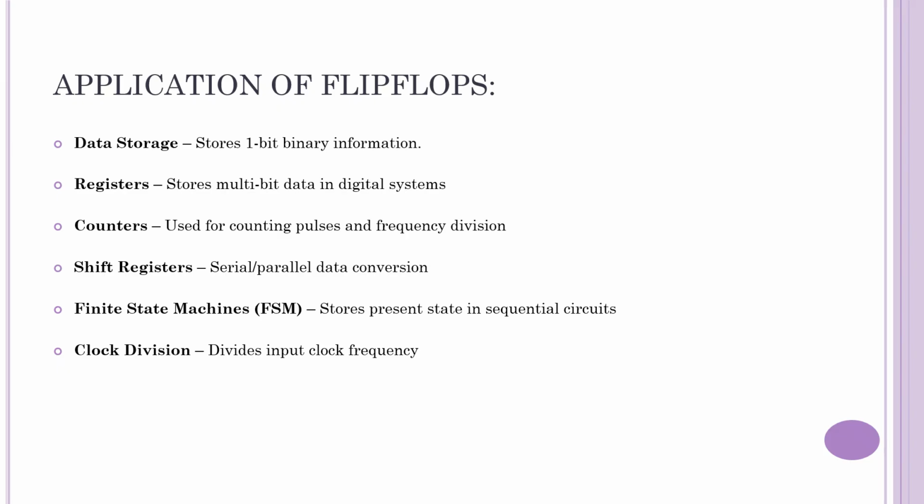Another powerful application is frequency division. A simple toggle flip-flop can divide a clock by 2, and with more stages, you get divide by 4, divide by 8, and so on. Now comes one of the most important applications, finite state machines. Flip-flops store the current state of the system. Control units, traffic light systems, communication protocols, all of them rely on flip-flops.